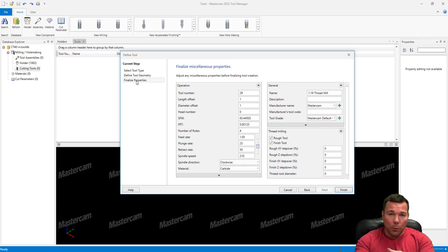I use tools 24 through 29 as tools that I could just swap in and out all the time. So I'll just pick randomly one of those numbers usually, and sometimes I'll have to change it when I'm programming, to a different number because I'll have two 29s, but generally speaking, it usually works out. So offset 29 makes sense. Head, I don't need to worry about that. I only have one head on this machine.